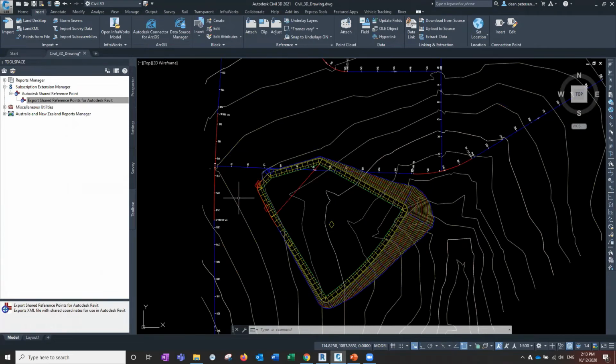This is the part that does need to use a Revit folder. It was always a problem in the past that when you exported just triangulations from Civil 3D, they would be retriangulated when they came into Revit. So things like these nice sharp pad edges would have the triangles broken.